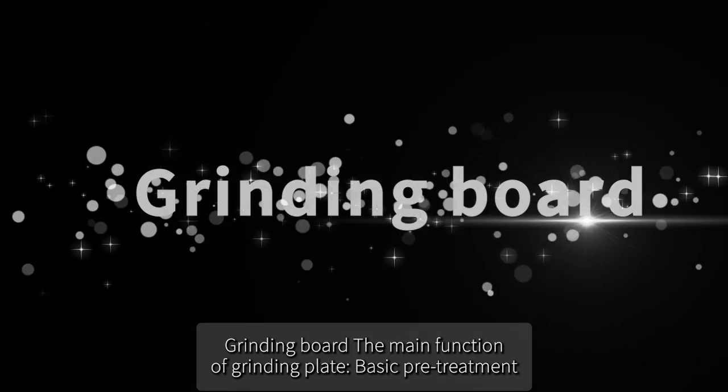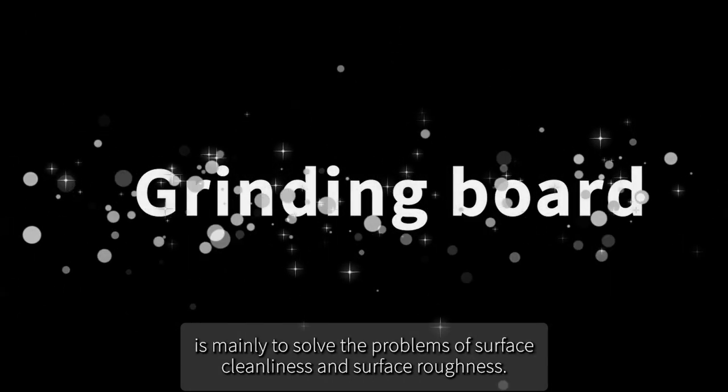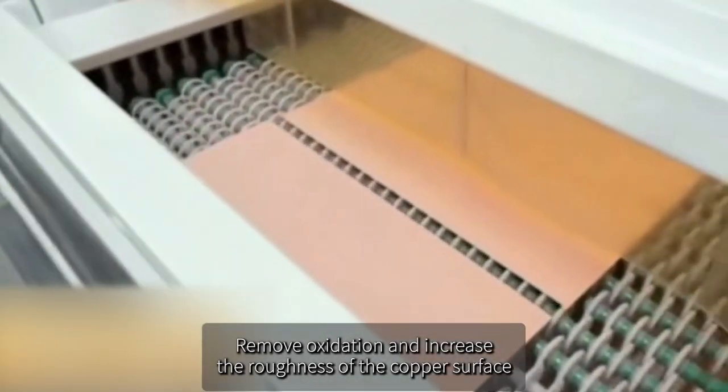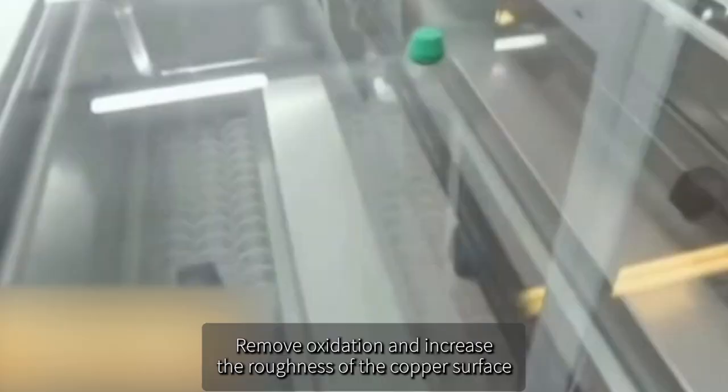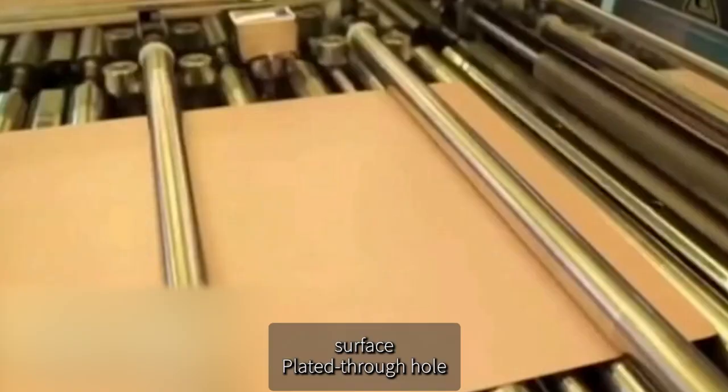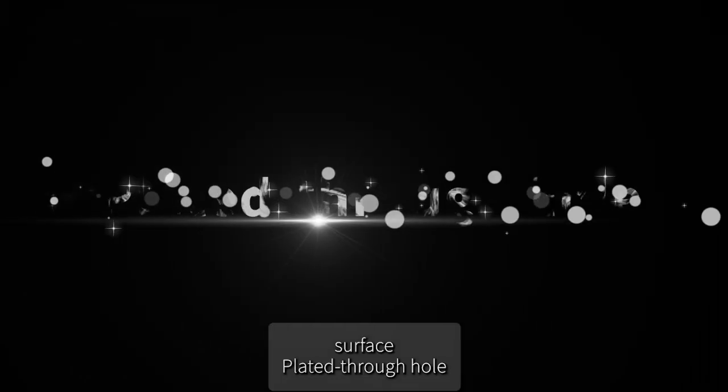Grinding board. The main function of grinding plate, basic pre-treatment, is mainly to solve the problems of surface cleanliness and surface roughness. Remove oxidation and increase the roughness of the copper surface, making it easier for the film to adhere to the copper surface. Plated through hole.